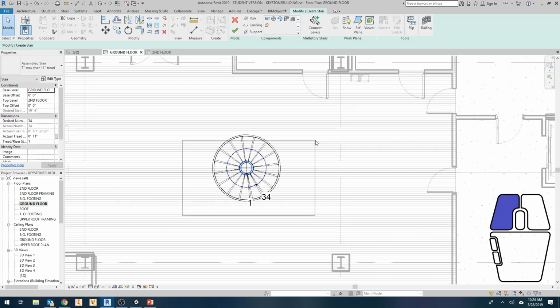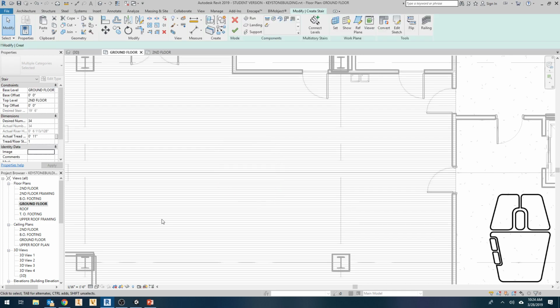It would be very hard to get down, yes. I'm probably going to require you, if your diameter is less than a certain amount for a spiral staircase, you have to have a second set of stairs to get down for egress purposes. Yes.